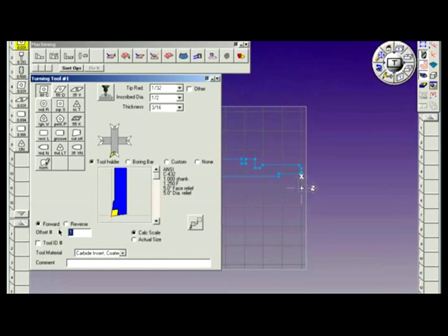The spindle direction is controlled forward or reverse. The offset number is based on the tile location in the tool list. If you have a pre-tooled turret and the first tool that you're using in your program in tool tile number 1 is actually in a different location on the turret, you can turn on tool ID, type in the turret location. For example, let's type in